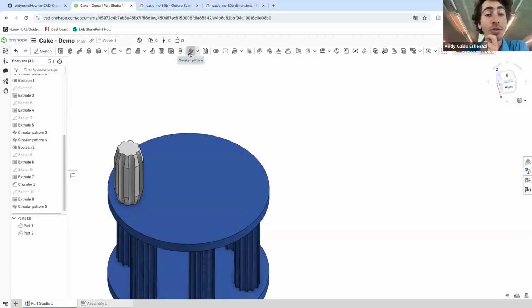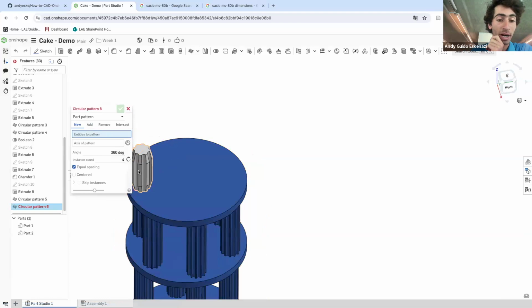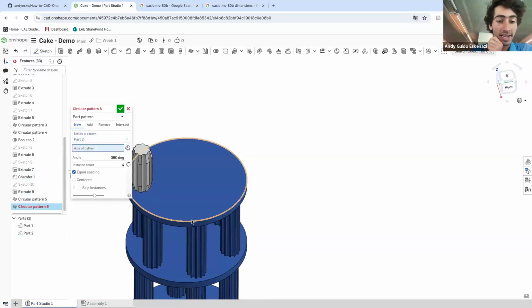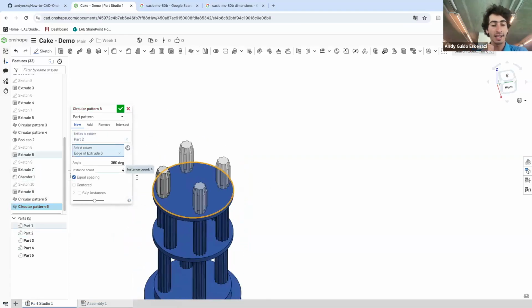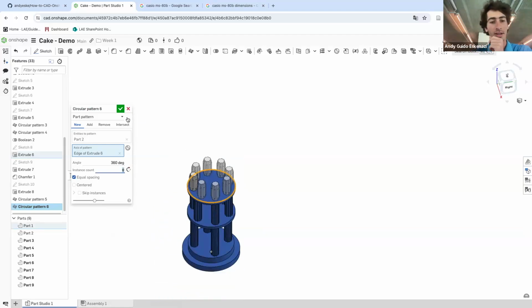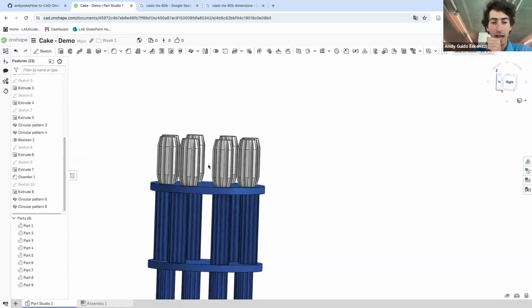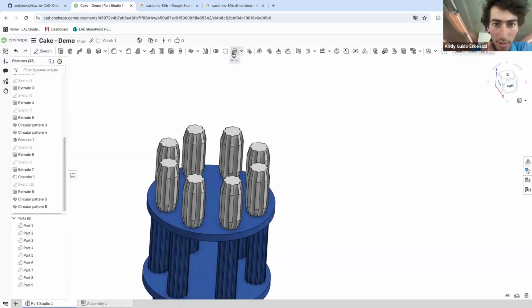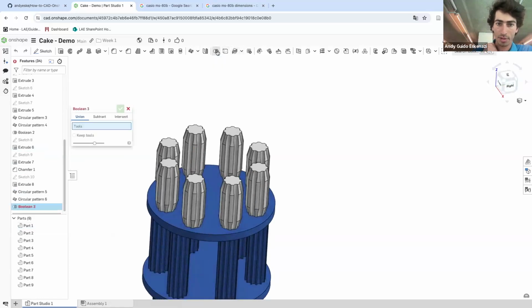Anyways, you do a circular pattern. So now a pattern of parts. So I click in here, and then the axis, again, like that one, and I can do, again, 8 of these columns. So we went on 4, 6, 8. Very good. And now, as usual, we're gonna make our Boolean, which is that button in there.